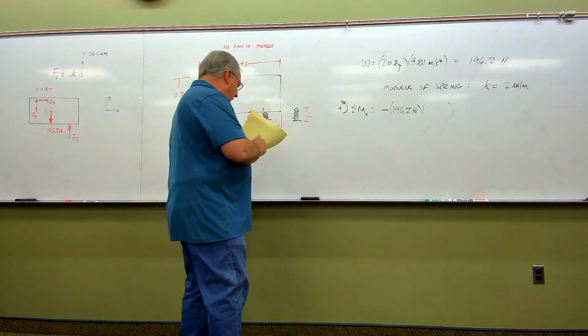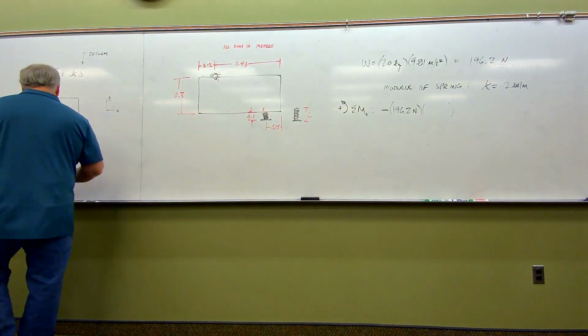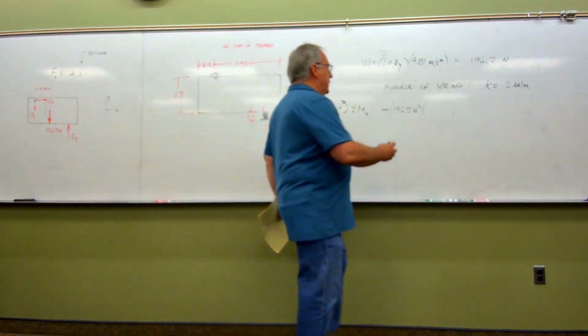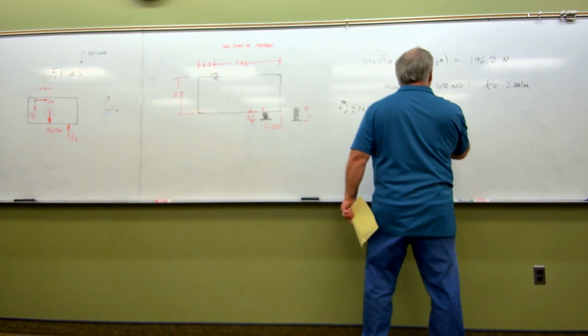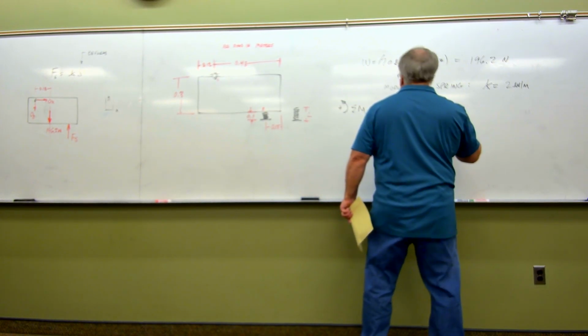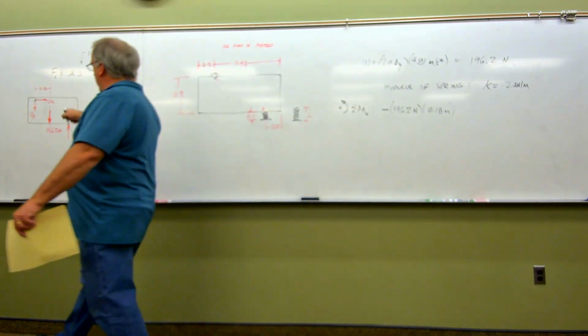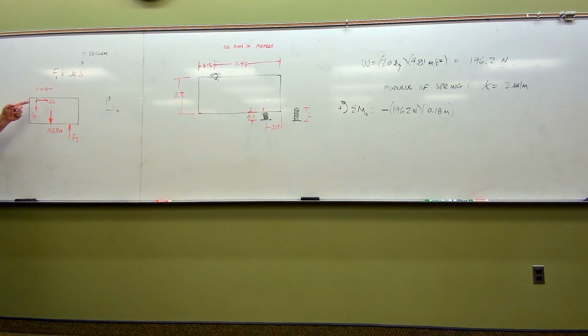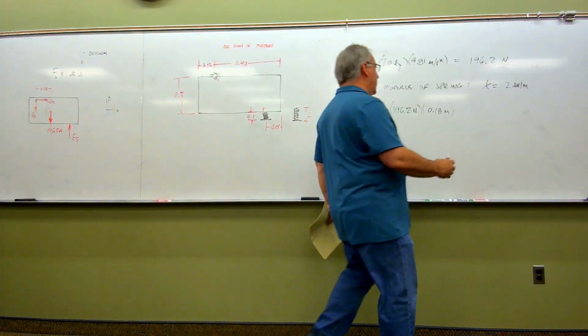So I'm going to come over here now to my equation. And I'm going to add my moment arm here of 0.18 meters. And that takes care of the moment due to this force. Now again, let's just reiterate, let's hammer this point home. OX is not in the picture, OY is not in the picture, because their lines of action pass right through the moment center. But I got FS over here. Now FS, the way that it's drawn, that's going to be causing a counterclockwise rotation, so that one's going to be positive. So back over here to our equation, we'll have plus Fs,